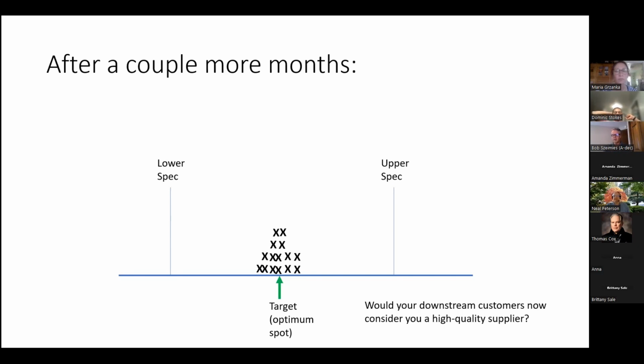Sure, there's a little bit of variability, right? Now, this road, again, is months or years to get this good. Sometimes you have processes with a lot of built-in variability, and you've got to figure out through designed experiments and stuff like that what process variables you need to change to narrow that variability, and use control charts to keep it in place, right? Yeah. So process experimentation will tell you whether you're improving or not improving your quality deliverables. Yes.